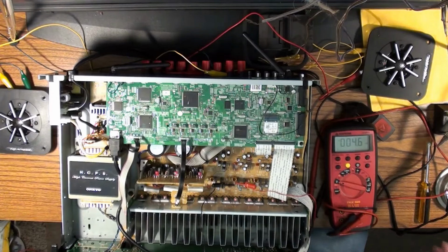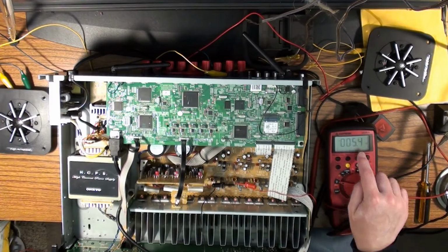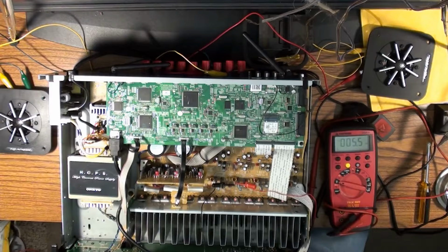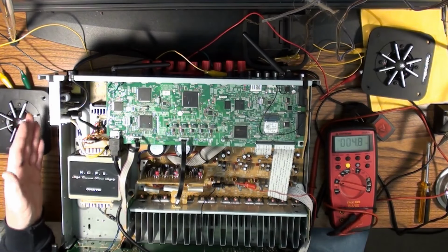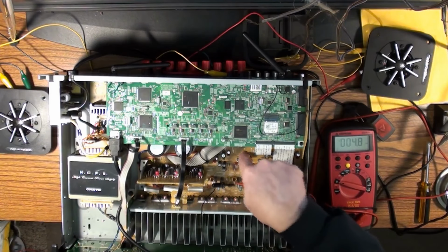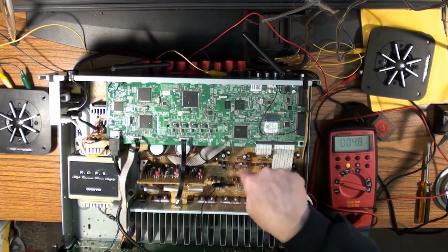And if we turn this up, which I have some YouTube free library music here, we can see that the number changes. That's why they have you set it with nothing playing, with nothing on, just heating up. So that's all the way down. Then as you turn it louder, that number will get bigger. You check it with it all the way down, and all of them are within, so we have nothing to worry about. And I have this one connected to just the left side, and this one is connected to the surround right channel, the channel that we replaced the components on.